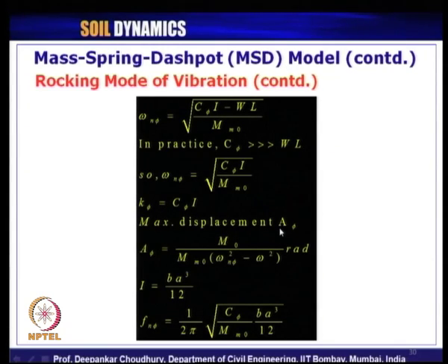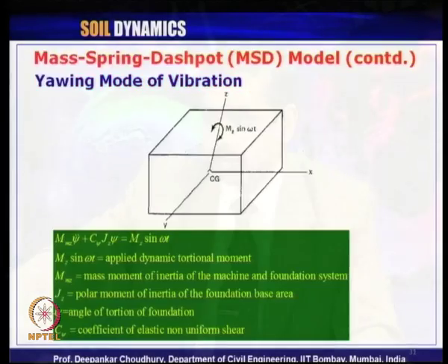If you multiply this with respect to your height, you will get the projected linear displacement, right. That will have to be checked against that 0.2 mm. Is this clear? So, if we multiply this with the height, you will get the linear dimension of the maximum possible displacement, that needs to be checked with 0.2 mm, which is the specified value.